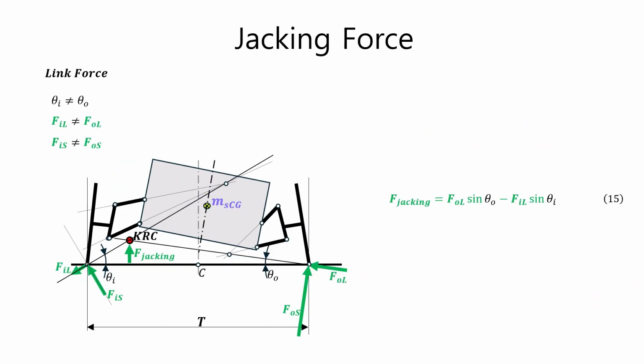The jacking force discussed above can be expressed mathematically as equation 15 using the forces FIL and FOL acting in the direction of the kinematic roll center KRC from the left and right tire contact points, and the angles θi and θo of these forces.